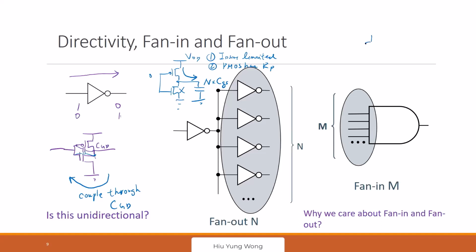If you have a lot of inputs, then you think about how you implement it, right? You have many inputs. Even if all of them arrive at the same time, I have n inputs. What is the function of a NAND gate or inverter? Here I have the so-called pull-up network, right? How do I evaluate? I evaluate by discharging this node, right? Let's say I'm at 5 volt. How do I bring this to 0 volt? I need to discharge the capacitor to 0 charge. And if I have n inputs, then the resistance is going to be n times. So that is a delay.